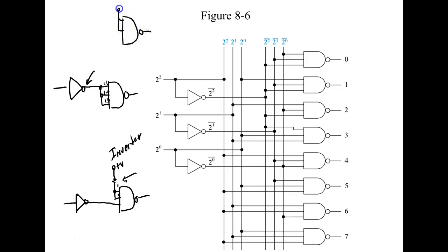So what advantage does that circuit have over this circuit? There I'm connecting it directly to 5. This one I'm connected to 5 volts through a pull-up resistor. And according to that, they do the same thing. This guy right here is dangerous to use because integrated circuits go bad 3 different ways. And one of the ways is these inputs can do what? They can short.